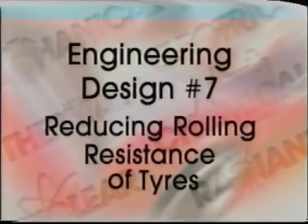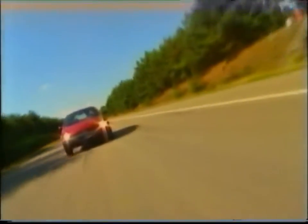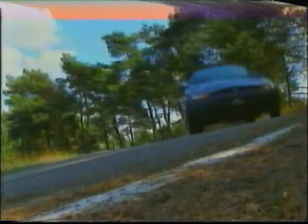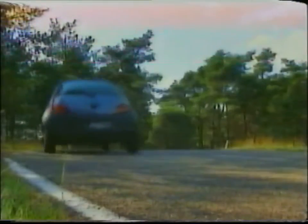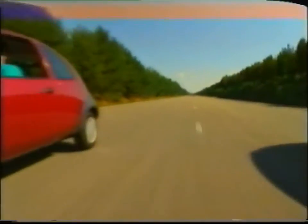Engineering design number 7. Reducing rolling resistance of tires. Reducing rolling resistance of tires with the road while maintaining safety is a task for engineers. This reduction is primarily achieved by manufacturing a lighter automobile. Less weight means less force between the tires and the road. Also, there is less flexing of tire materials, which causes the production of thermal energy. Tire pressure, design, and composition can also reduce the transfer of motion into thermal energy.